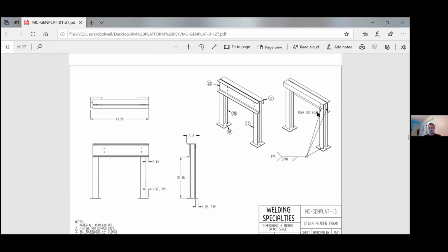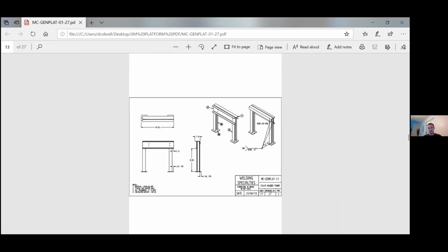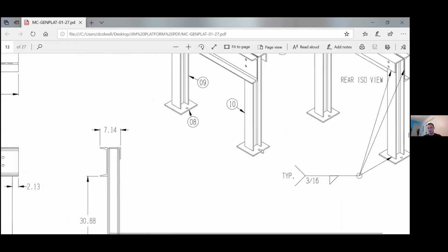I like to point to as many things with one weld symbol as I can though, because they can really clutter up a print. Take advantage of the typical, take advantage of all around, because if I had to point to each little location, a great example, I think, is this foot being welded to this I-beam. I could say, well, I only need this side and this side welded, but unless I'm really worried about the time it takes, why not just weld it all the way around? And so I can just point to that one place, and I've welded this entire plate all the way around the I-beam. Anywhere there's a weld seam, this thing's getting welded.